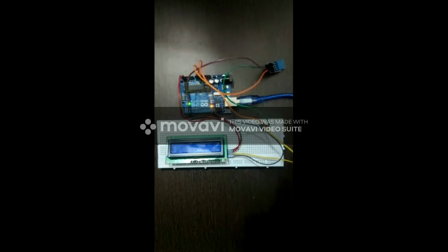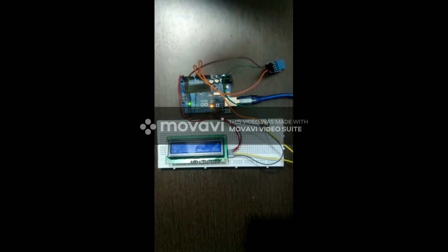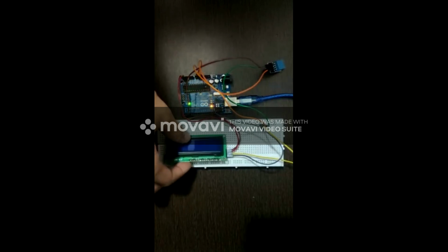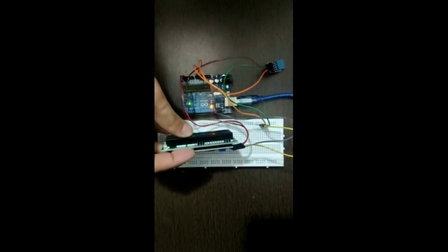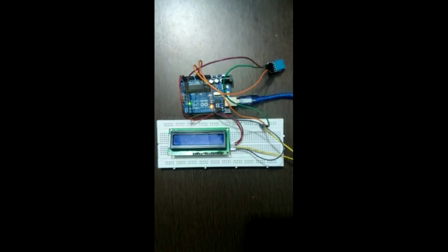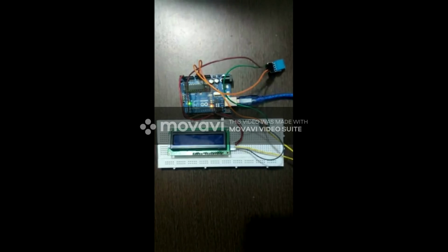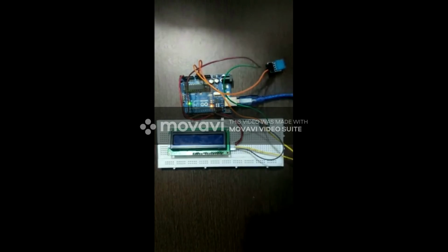These are the components that have already been assembled together using jumper wires. These components are the DHT11 sensor, Arduino Uno board, I2C module and LCD display of 16:2 that has been soldered together, and a breadboard. In this, using jumper wires, we connected the negative pin of the DHT11 sensor to the GND pin on Arduino, and after that the out pin on the DHT11 sensor to the 2 pin on the Arduino.